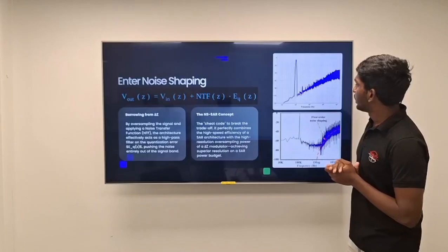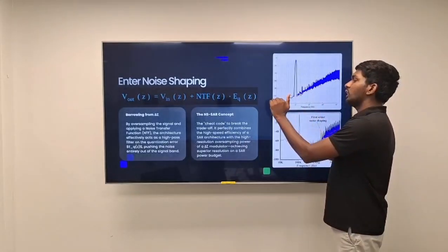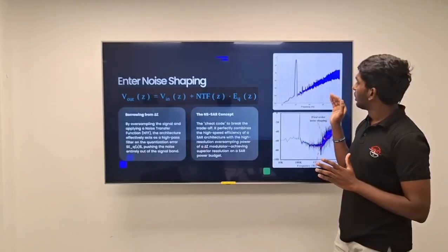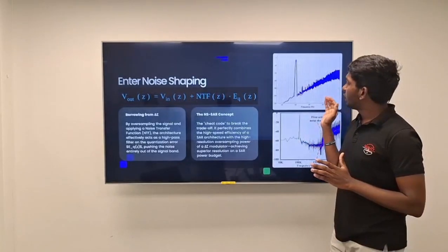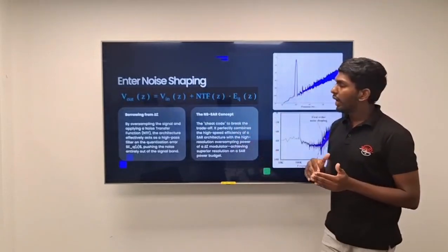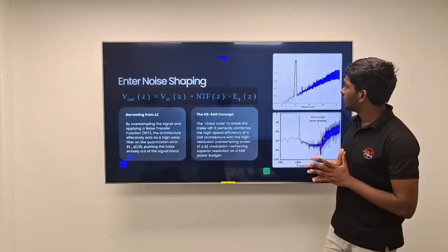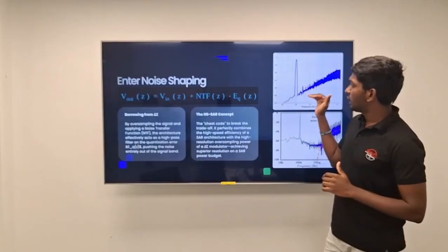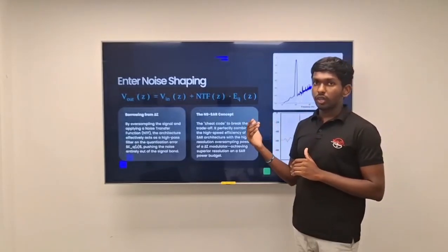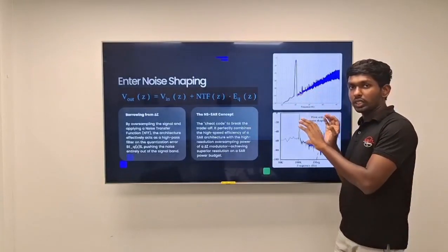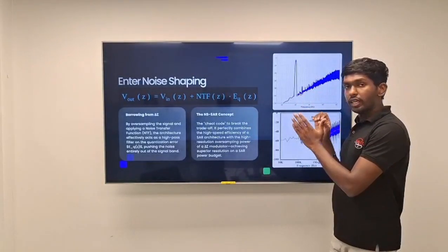By doing this, we are able to achieve higher signal to noise ratios with a simple comparator and smaller capacitor sizes. So what we are doing is oversampling the signal, like in the delta sigma modulator, and having the normal SAR in the core.